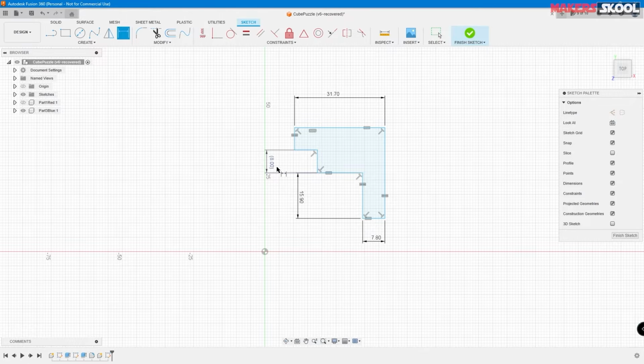You can see that the sketch length is 8. The driven dimension is for reference purposes only. It means that this dimension is not driving the sketch. It's like measuring this length. It's shown by the brackets around the 8, which means it's for reference only.